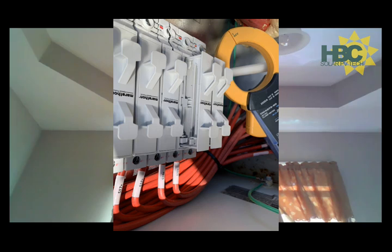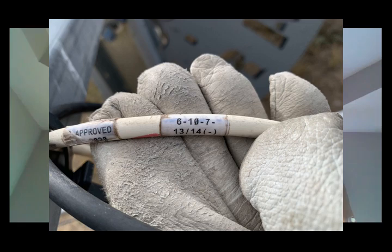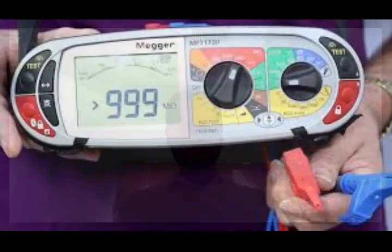Verify that no current is flowing in the circuit using a clamp meter like the Fluke 325 True RMS clamp meter, 378 non-contact AC/DC clamp meter, or the 393 solar clamp meter. Cut the conductor and remove any damage. Place a positive connector on one side and a negative connector on the other. Plug in the connectors, ensuring that they are all firmly in place. Repeat voltage and/or insulation resistance testing on the circuit to verify the repair.